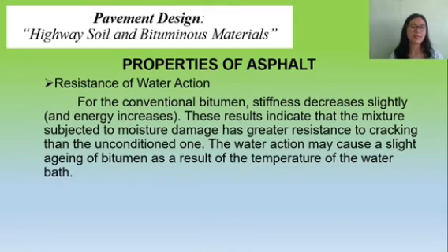And lastly, we have the resistance to water action. For the conventional bitumen, stiffness decreases slightly and the energy increases. These results indicate that the mixture subjected to the moisture damage has greater resistance to cracking than the unconditioned one. The water action may cause a slight aging of bitumen as a result of the temperature of the water bath. So when the stiffness increases, also the energy increases. For this type of mixture, the effect of the water results in slight aging that is not enough to cause severe damage. So it is really okay for that.